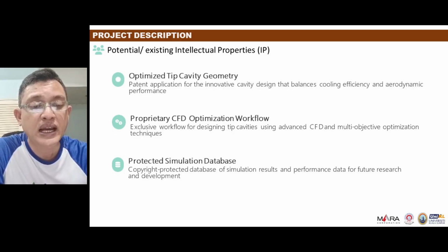This flexibility allows realization of intricate internal cooling channels, sharp cavity edges, and shapes tailored to enhance airflow and thermal management. Such complex designs are key to achieving improved cooling performance and aerodynamic efficiency, features often impossible or prohibitively expensive to produce using conventional machining or casting.